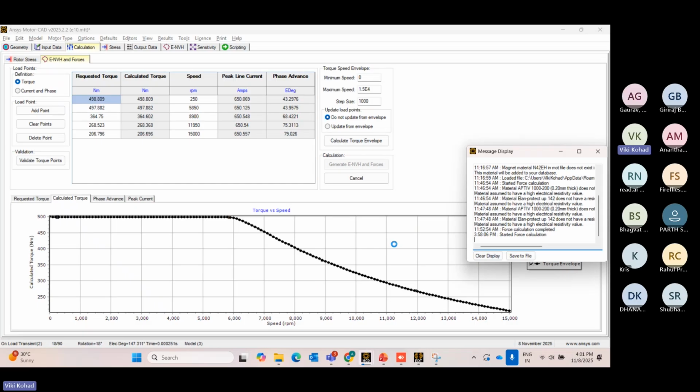Here you can consider your electric motor as well as the inverter harmonics. So here you can simulate the inverter, and on the basis of the inverter values, you can see the harmonics there in the ANSYS Twin Builder, not in the ANSYS Motor-CAD. If you want both the harmonics, then you have to couple ANSYS Maxwell with the ANSYS Twin Builder. So you will get both values on the harmonics.